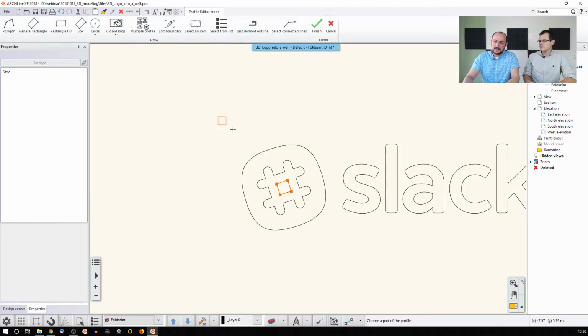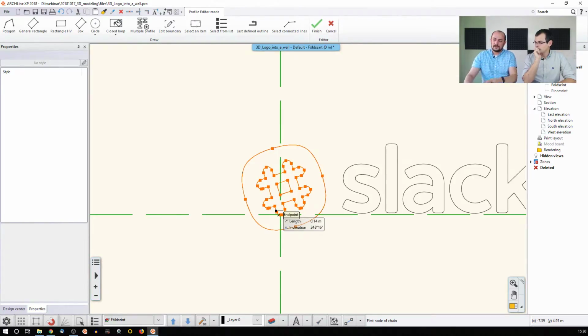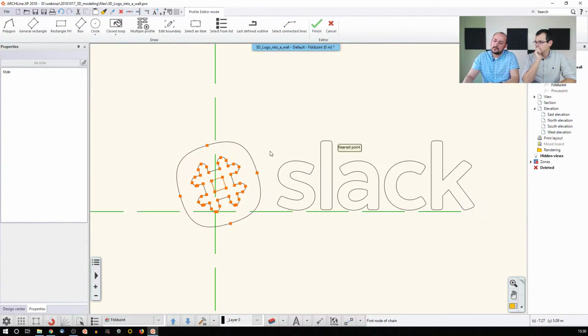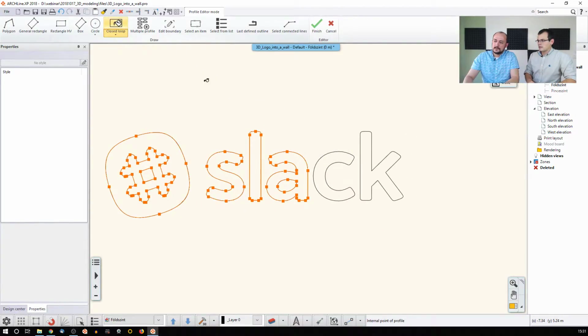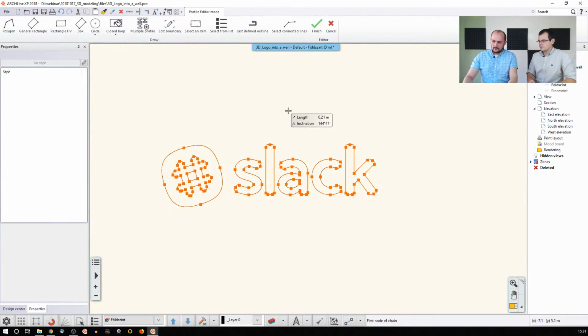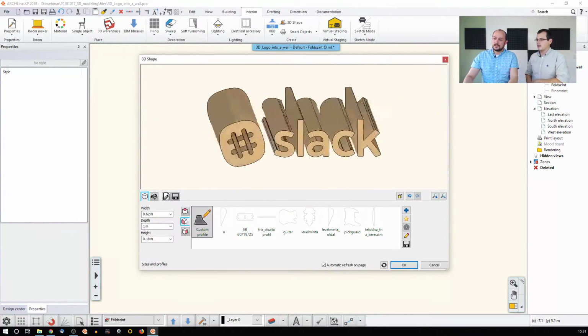So when I click here and I click into this shape, then the software recognizes it, and it's avoiding the floating island, skipping it. And then I'm going and saying, okay, this is another one. And another one, and this is again something with an island. There's an island in it which you don't want to include. So let's just select that, and this is again just a closed loop, and I think this has no island, so I just go with this one, and then I'm done. I'm just saying, okay, finished, enter, and then it turns it into something like this.